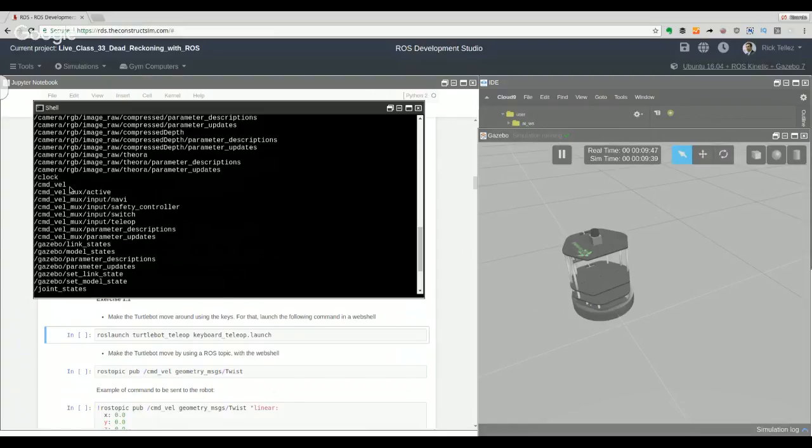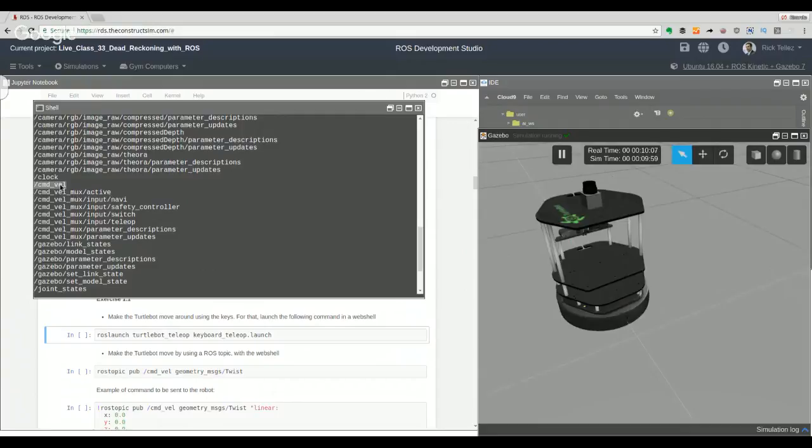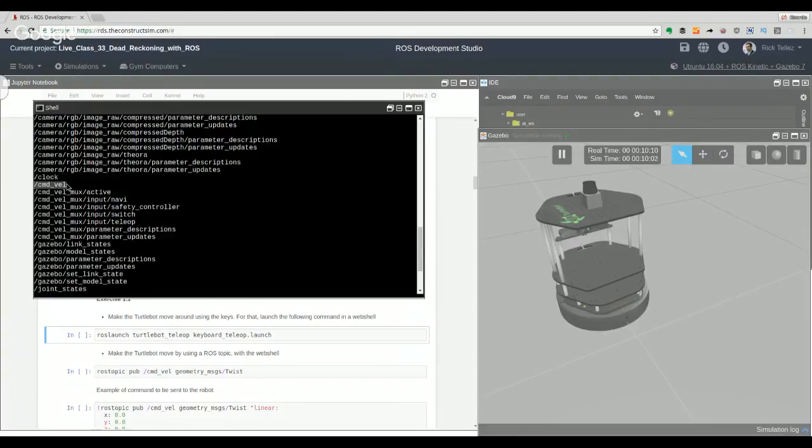There is a ROS program already made by the Turtlebot people that listens to this topic, and whenever it receives the linear and angular velocity, it translates them into the proper motor commands. You don't have to care about how this is done because it's done in the robot itself. All the ROS-based robots provide this already, so it's super cool because you don't have to care about that.